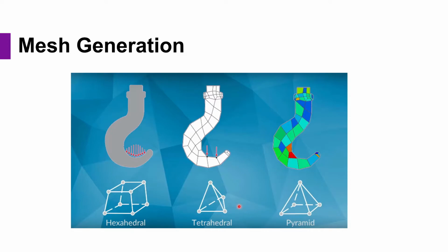The reason we have fillets around products is that you will be able to manufacture them more easily, using a milling machine or face milling machine, for instance. It would be much easier to work with these curvatures rather than having sharp lines.